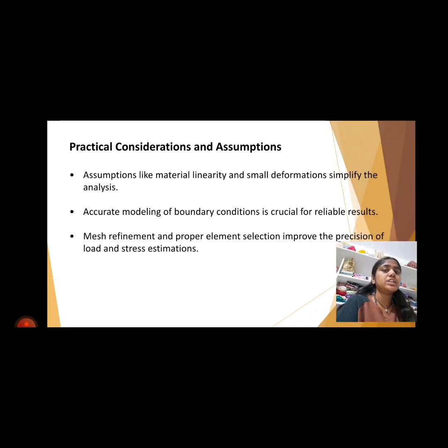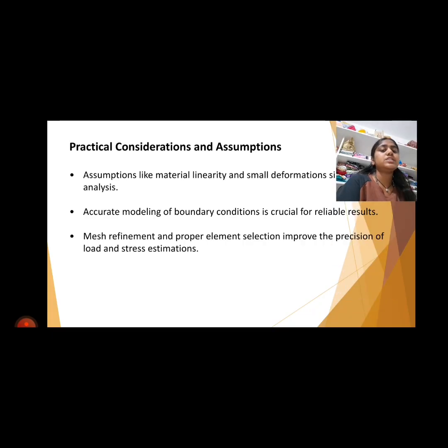Practical considerations and assumptions. Assumptions like material linearity and small deformations simplify the analysis. Accurate modeling of boundary conditions is crucial for reliable results. Mesh refinement and proper element selection improve the precision of load and stress estimation.